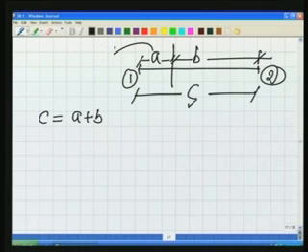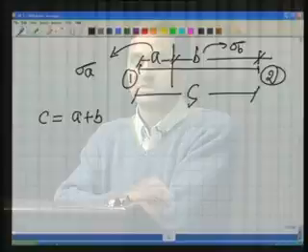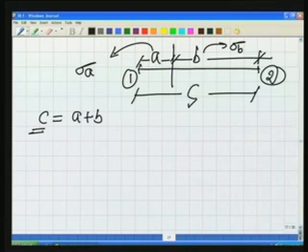A had a standard deviation of sigma A, similarly B had a standard deviation of sigma B. How do we know these standard deviations? For example, this B was measured, let us say, 10 number of times. You have 10 observations for B. You can compute the mean, you can compute the standard deviation. Similarly for A. Well, we know the length, but we do not know what is the confidence yet.